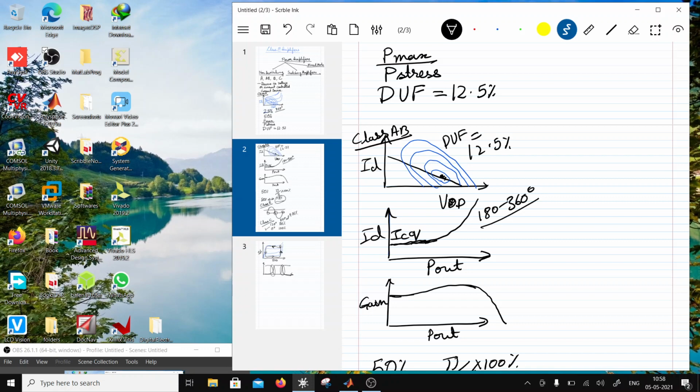But once you hit it with power and it starts compressing, the drain current goes up, and the device parameters are going to change on input and output. So the idea is that you should be best matched at compression, as we have covered in the previous session on PA, which you can refer to.